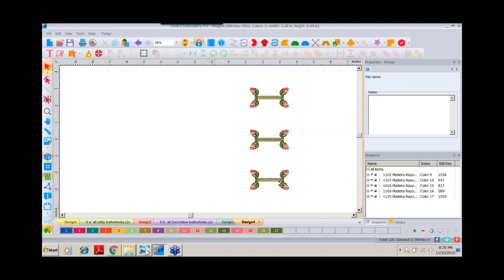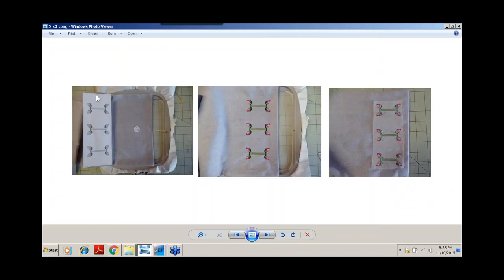If we move forward with the process, we have a template again. You would do your print preview and print that off. This one I did not put in the crosshairs, but you can see I still used it to mark the center of the completed scarf. Once again, you have to create the scarf first, and that really is just a matter of cutting out your 2 pieces. If it's finished at 34 and 8, you would probably cut it at 35 and 9 and use 1/2-inch seams. That's what I did.